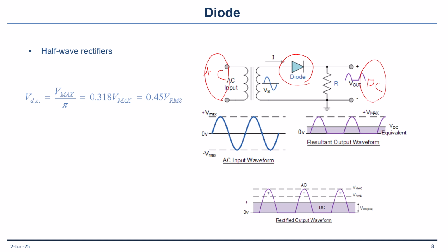For example, television, laptop, phone, or anything like that all work on DC, but the plug that you have in your home operates on AC. So you cannot connect them directly, and you need a rectifier. The rectifier cannot change the RMS value much, so the RMS value should stay the same.